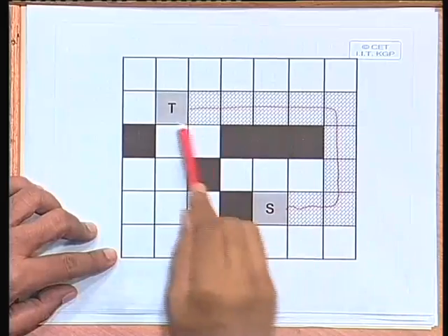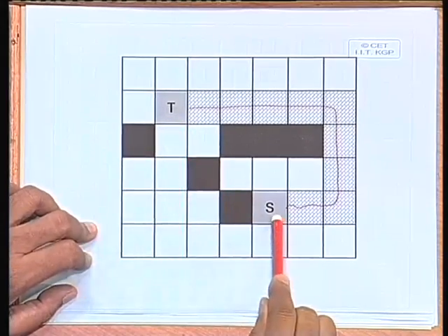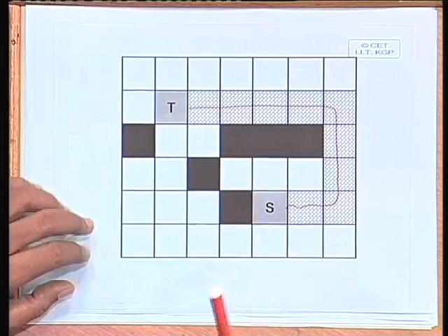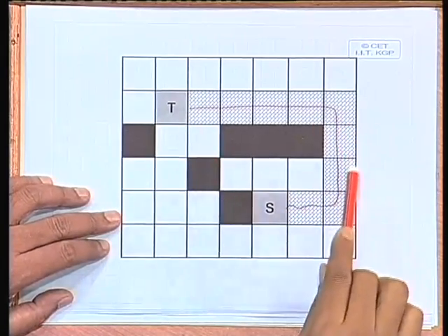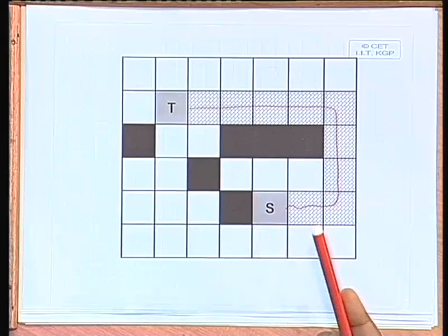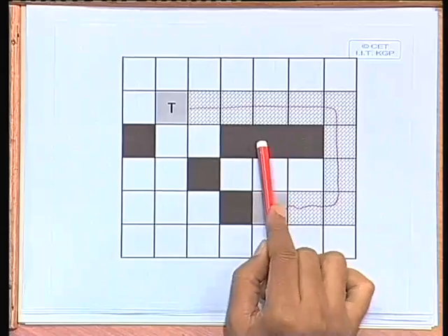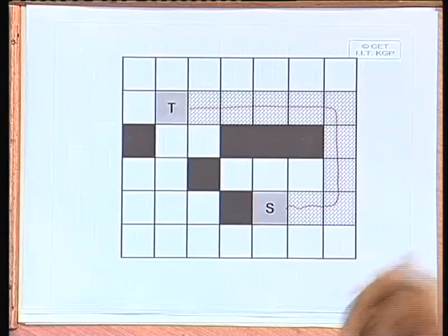Now, obviously, this is not the unique path, there are other paths also, this may be better or this may be shorter length also possibly. So, there can be multiple paths to it. So, the problem of grid routing attempts to find out one path. Well, we will want that the path is as good as possible, if possible minimum cost. There can be other nets also which will be acting as obstacles. In the order in which you lay out the nets, that also becomes very important, because once you lay out net number I, that will act as obstacle for net number I plus 1.